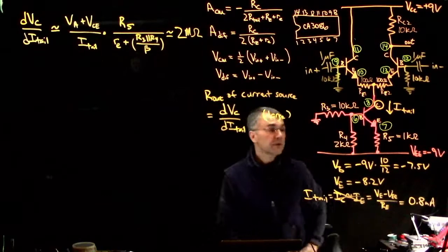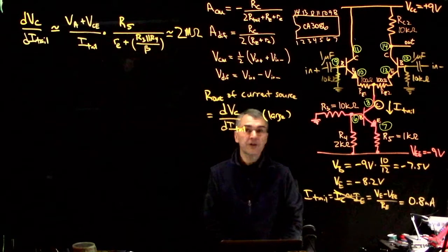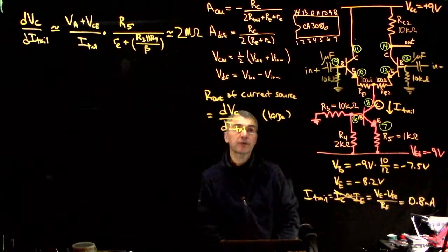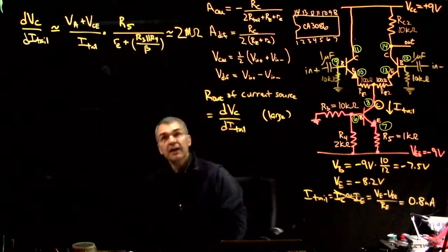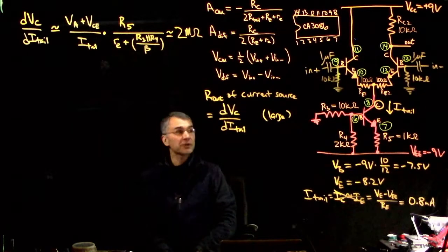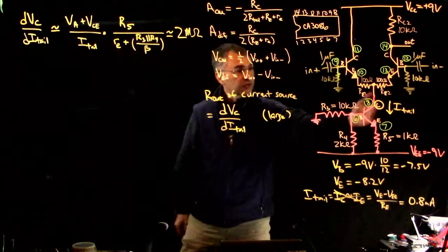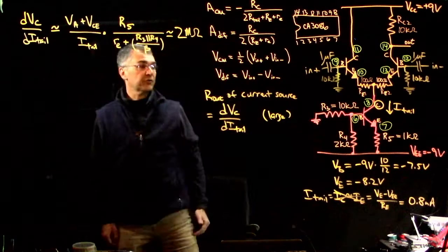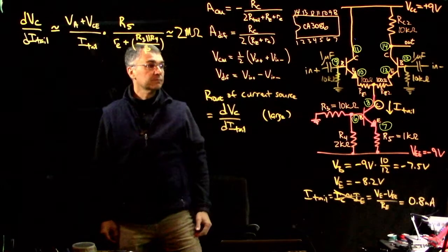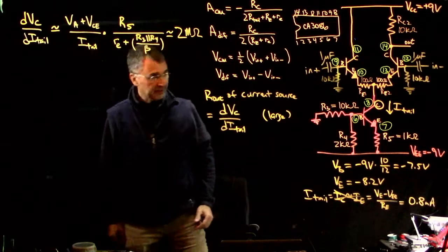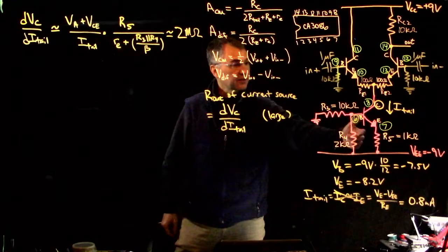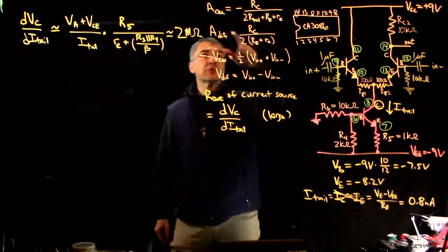Okay, we are finishing up. We're doing the last part of the differential amplifier for lab 16. And we just replaced the tail resistor in this differential amplifier with a current source. The reason we did that is we want to reduce the common mode gain even more.